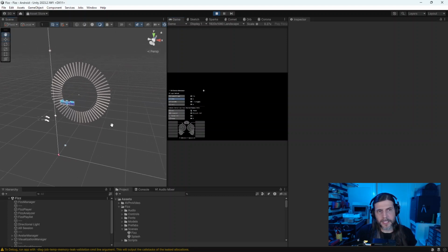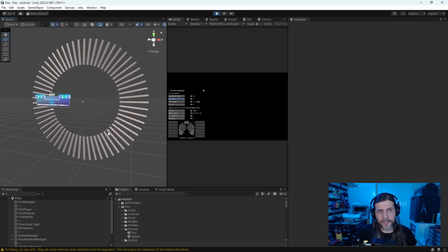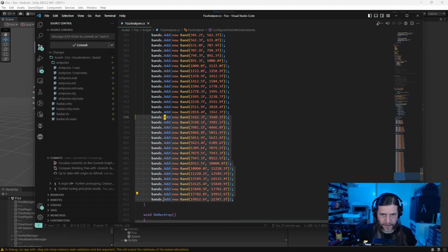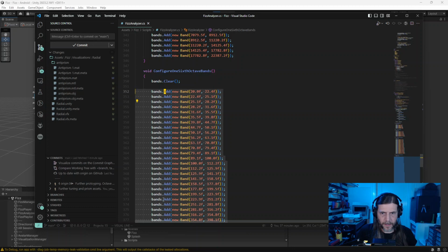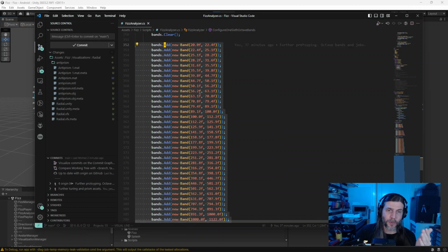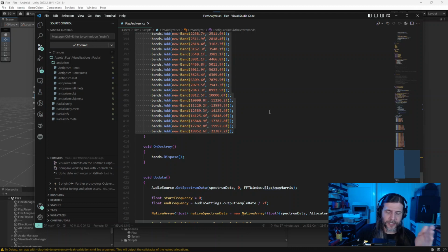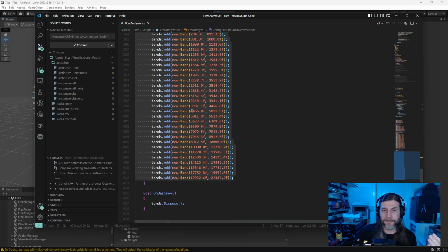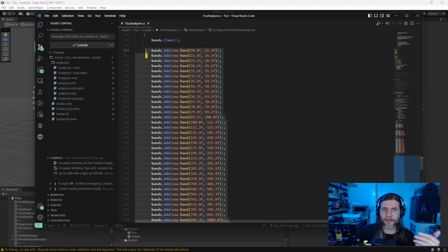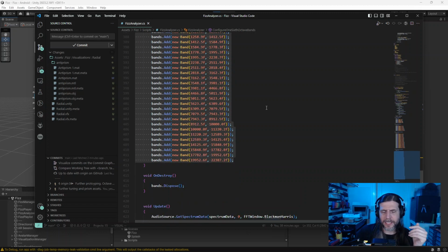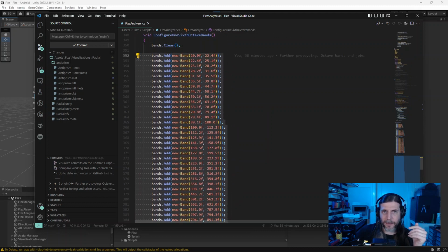This is the sixths of an octave. I don't even know how many bands we have here. How many bands do we have here? 61. Kind of tempted to add a few more bands to get it to 64, even though we'd be going a little low. I tried to include the range 20 hertz to 22050, which is based on the Nyquist formula, half of the sample rate. There's the range of human hearing, and then there's the range that you can reasonably do the spectral analysis on, which is about half of the sample rate. Anyway, so there's about 64 bands here. There's a little bit less. Maybe I'll fluff it up.